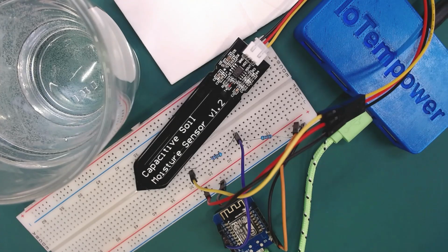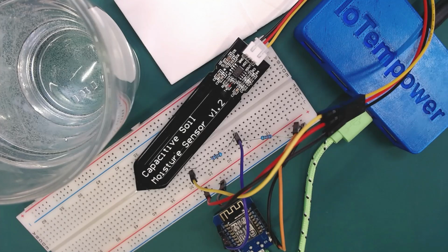to get that down. This device needs 5 volts, and this is why I have to protect the output and take resistors to lower the value here. These are just two of the same resistors, so we basically get an output maximum from 0 to 2.5 volts, but the interesting area I know already in advance is between 0 and 1 volt.